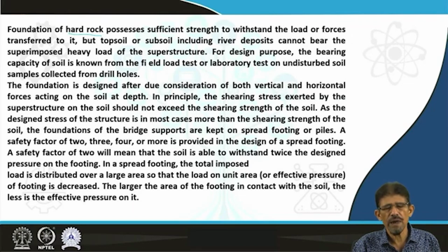In the case of foundations on rock strata, we expect minimal problems, and problems may arise if there is a presence of some seams, some pockets of weathered material, unconsolidated materials, some weathered zone, or some strata prone to swelling, etc. If such hazardous zones are available in rock strata, then careful preparation and treatment and suitable measures are required to strengthen the rock strata for supporting the load of the planned and designed bridges.